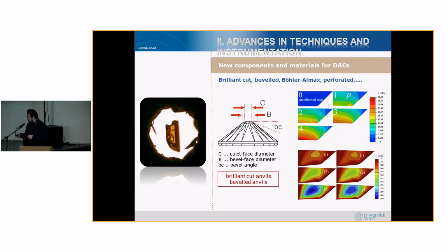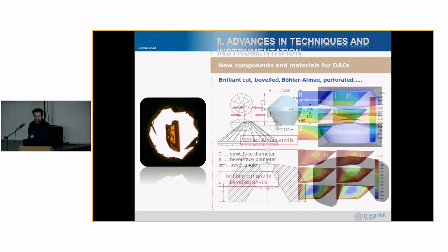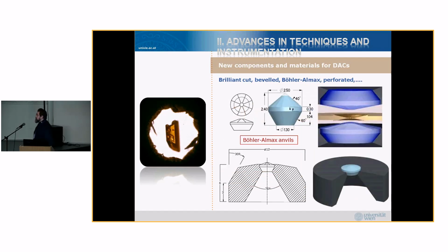So one thing to overcome this is to round the tip. That's something that has been used for the last 10 years already, or maybe even 15 years, the so-called beveled angle. That means you see here there are some extra facets. These are the so-called bevel facets here, which is a modification to make it more round, because your tip, if it bends off, does not have these angles here, and it's flattening out in the regime of these megabar pressures.